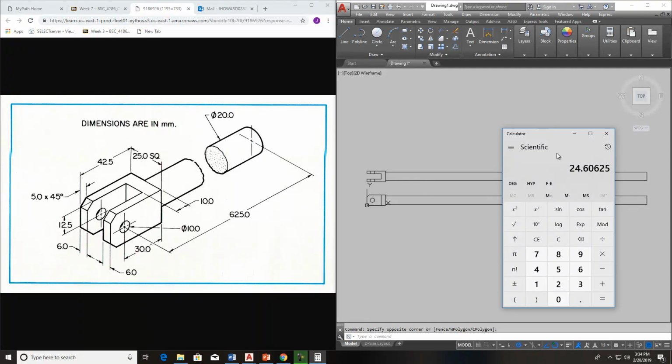That's the reason we're going to use this break: we've got a lot of features here, but it's so long that when you put it on a sheet, you're not going to be able to see these big features very well, because of the length of this shaft. Or any part that's very similar to this, you can use breaks. Let's get in here, and I'll show you how to do that.